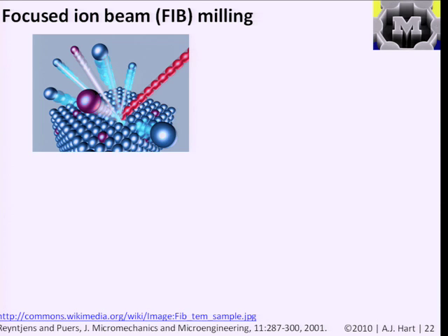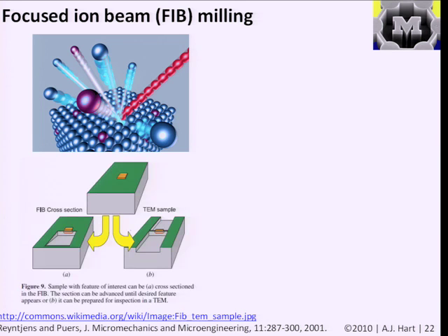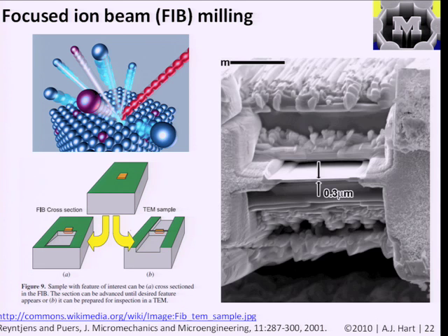And another prototyping process that we saw before, just to show it to you again because I think it fits into this category, is that you can use beams of light or electron beams to modify materials. You can also use beams to physically remove material. For example, focused high-energy beams of ions, called focused ion beam milling, can be used to cut materials at the small scale.